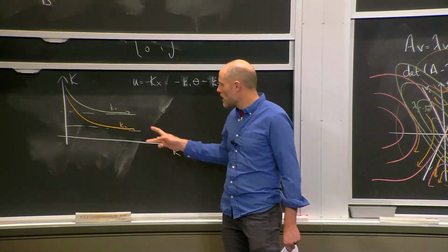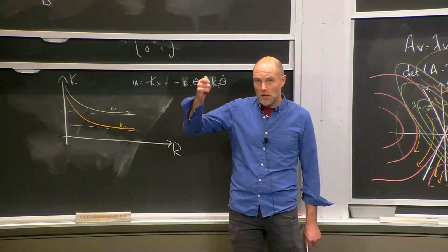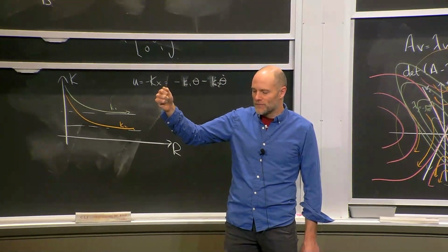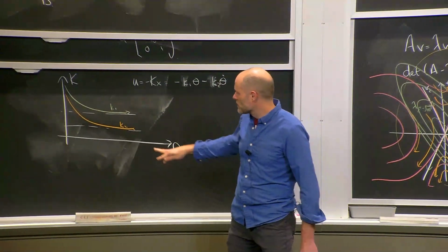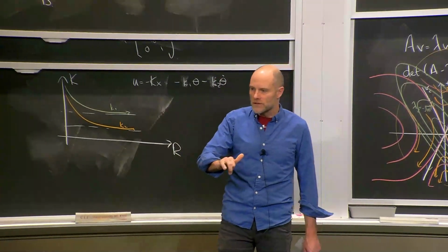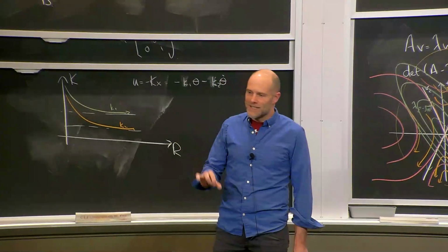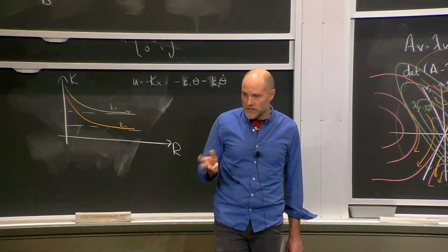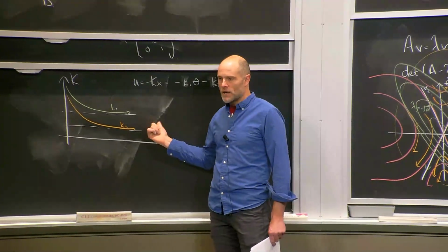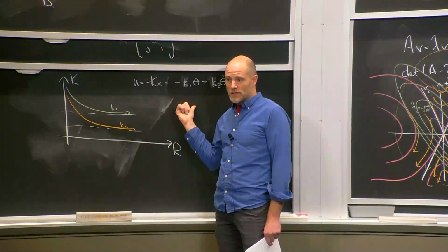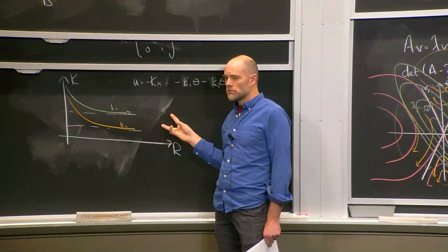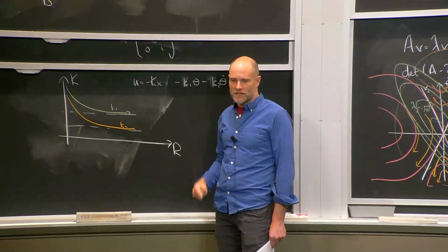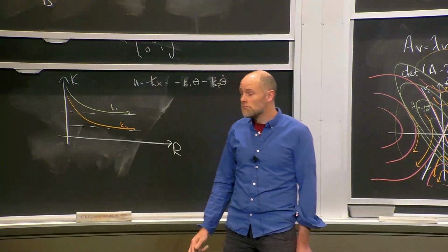My intuition is if you crank up R very, very high, say really try not to use any energy, it'll put it closer to the boundary of stability, then you're going to be more sensitive to model errors, right? That's not a common problem. This is an extreme asymptotic argument we're talking about. But I think you're probably right. I would guess if I plotted the eigenvalues as R goes to infinity, that it's probably going to 0. But I don't know that for sure. I'll check that. Great question, yeah.